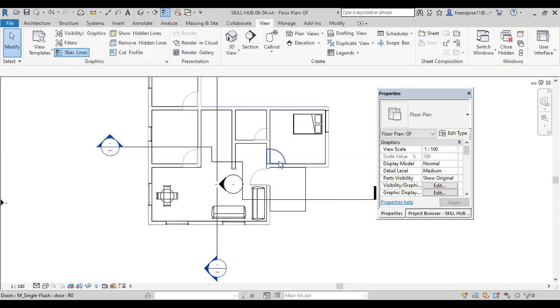For example, if you wish to create a furniture plan, the furniture has that much line weight and the rest of the portions have different line weights, whatever the settings may be. In the furniture plan, you input the measurements of the furniture positions only. The floor plan needs the measurements of the walls and rooms and so on. At that time, you create a copy of that floor plan and then make the changes. But the important factor is that all the model categories remain the same, and we can control the visibility.